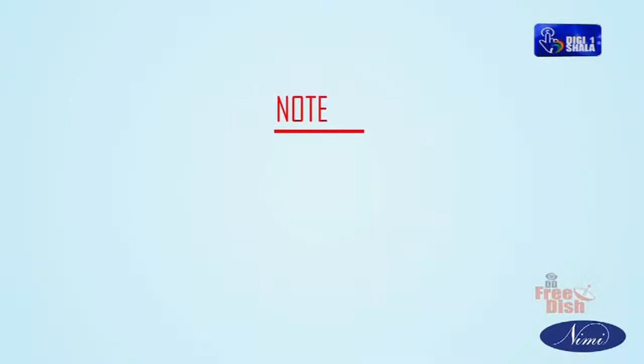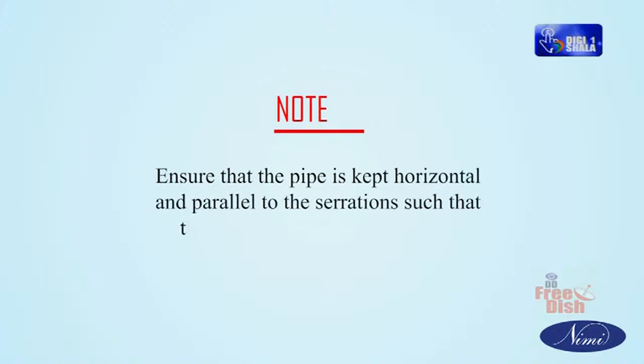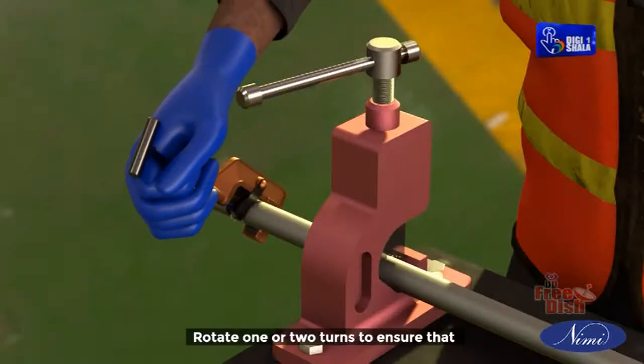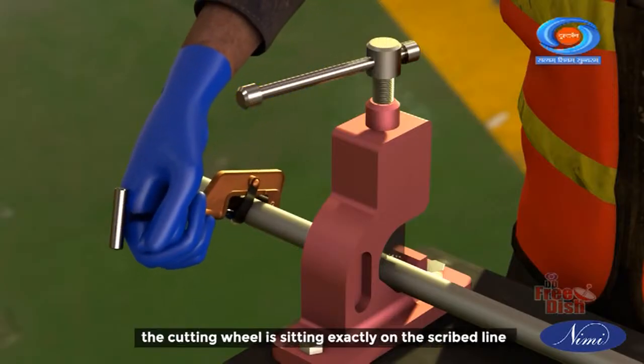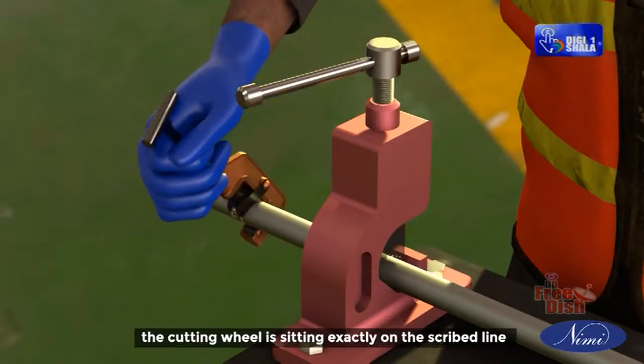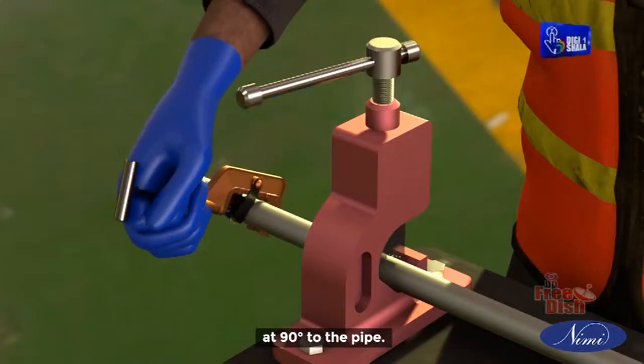Note: ensure that the pipe is kept horizontal and parallel to the serrations such that the marking is visible at the top. Rotate 1 or 2 turns to ensure that the cutting wheel is sitting exactly on the scribed line at 90 degrees to the pipe.